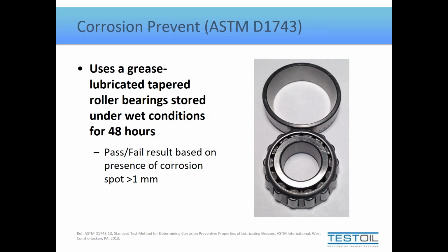So it does make it a bit difficult to compare two failing greases, because you have no idea the severity of the failure, whether one failed from one single dot and the other one failed due to complete coverage. But if it passed, it means there are no dots greater than 1 millimeter. So a passing result can be viewed as a good grease. A failing result is a bit subjective. You don't have enough information to really pit one against another one.